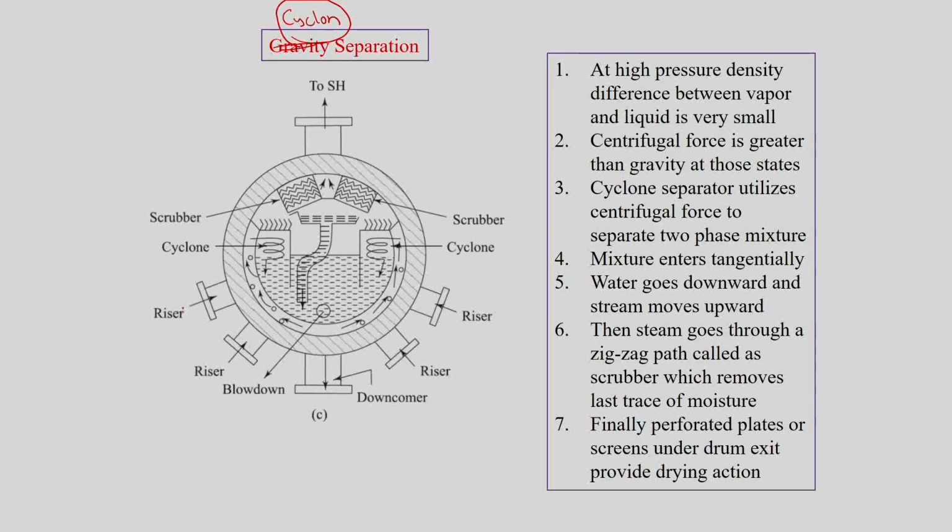In such a case, gravity or mechanical separation would not help. Centrifugal force becomes the prominent way to separate the two small density states of water, one liquid and one vapor. So, from the riser we will get a steam plus liquid vapor mixture,